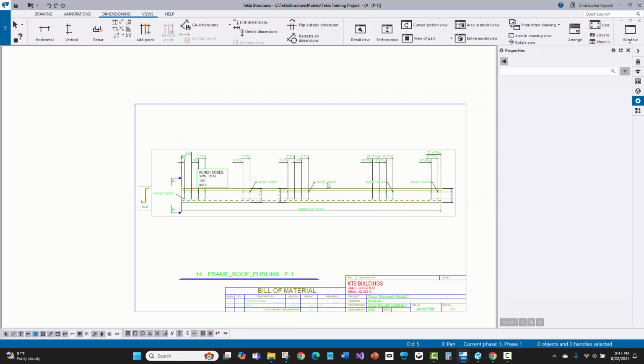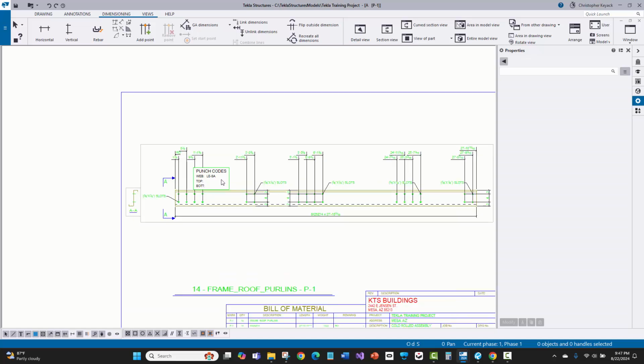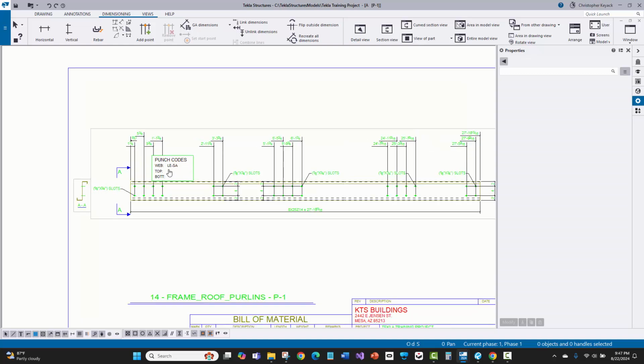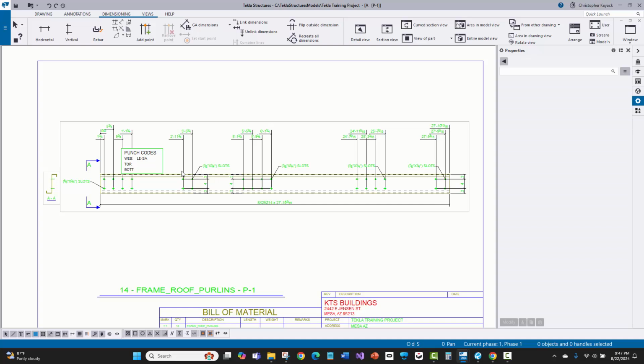If it does have welding on it or something non-standard, then MBS will make a drawing. But unless you tell MBS to specifically do this, it won't by default usually make drawings of cold form that don't require drawings, because the shipper will take care of that. But that's my way of confirming that everything in Tekla is matching the output from MBS.